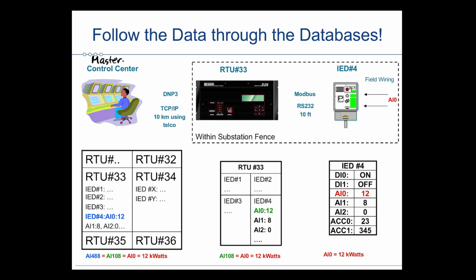Any automation goes on locally within specific PLCs, DCS, or other automation type networks. When it comes to SCADA, it's really just about retrieving data, statuses, and analog values from remote locations and bringing them back to a master control center where system operators and chief engineers can do the controlling of the process or the system. So that's what we have going on here.